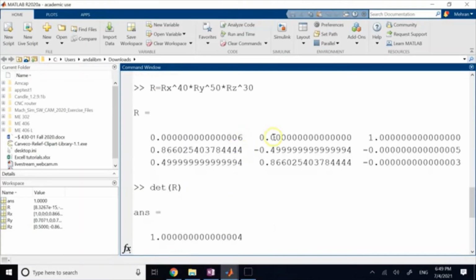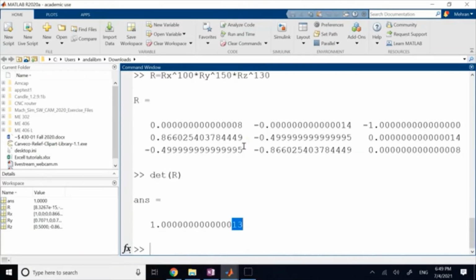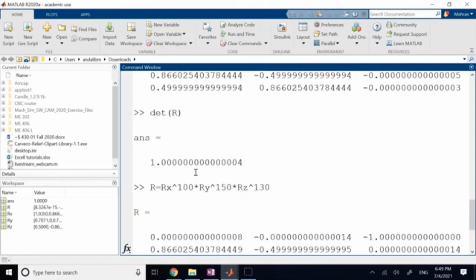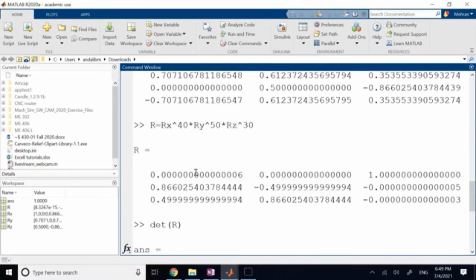And so if this process is continued and once in a while you don't reset and calibrate your system, not calibrate, but reset and home it and make sure that exactly you can go back to 0 and restart calculating R's, this error starts accumulating, and now these non-zero numbers are getting closer and closer to your major decimals, and once they get somewhere here or so, now you do not really have much of a good rotation matrix, okay?